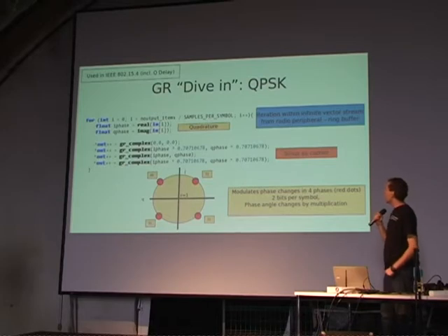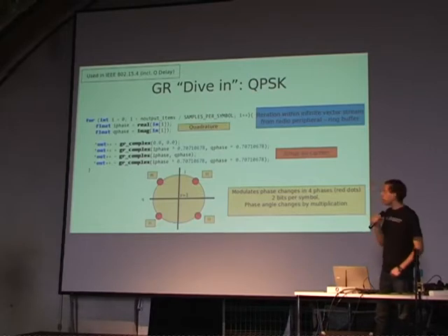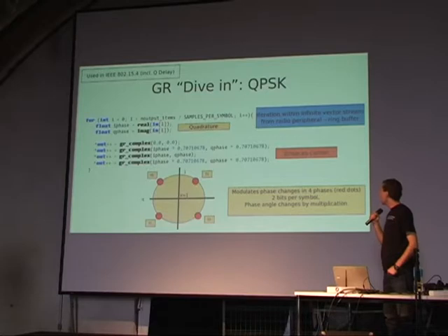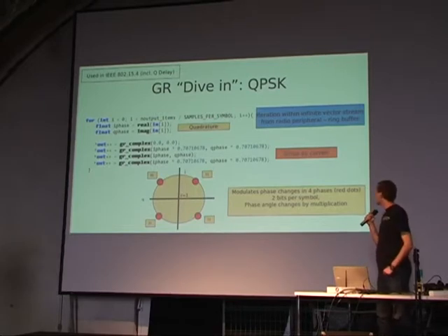And under the loop, so that's the loop head. Under the loop, we see that there are two float variables defined, which are I phase and Q phase, which are the quadrature signals. And the rest is the sinus as a carrier, which we see here, and it's using square root 2 divided by 2 to actually modulate on top of the sinus.